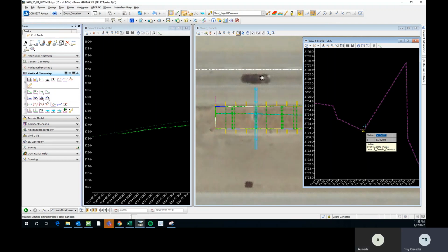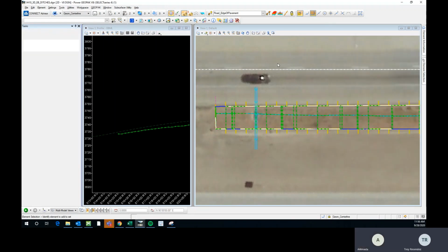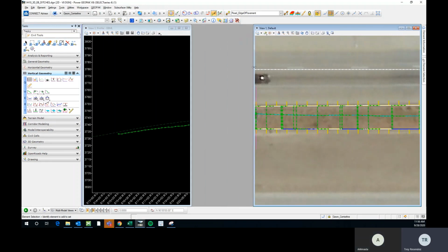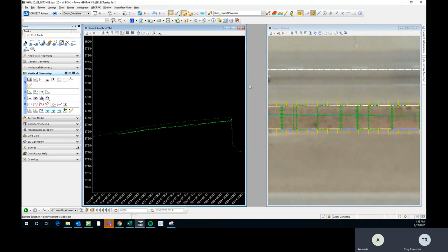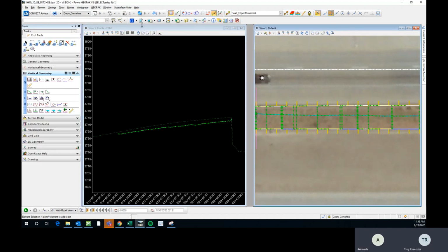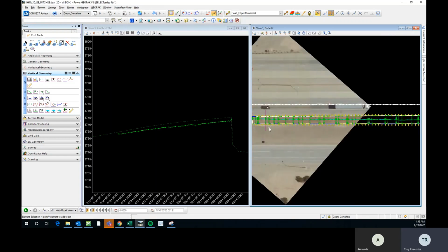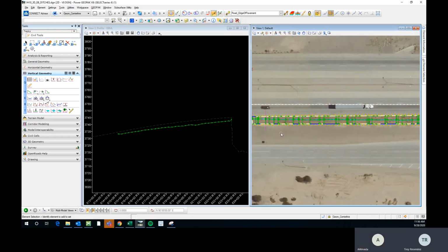37, 34, 25. So this is the inlet elevation that we want to hit. We actually want to be 1 foot below. Is that right? It depends on the ditch, but yeah, most likely. So we'll just go 1 foot below for now, and then we'll go from there.